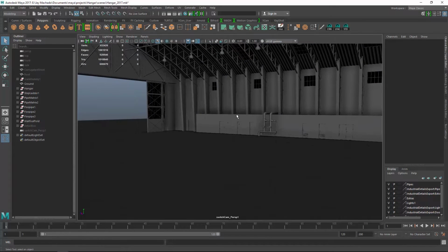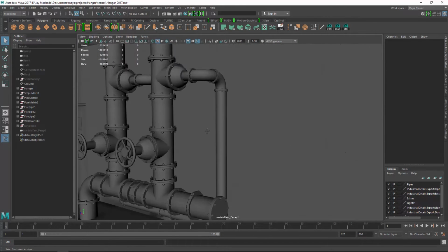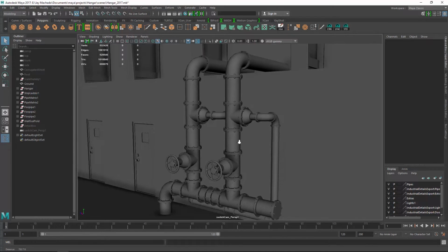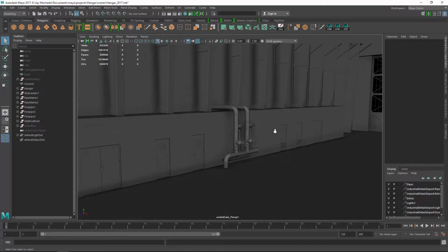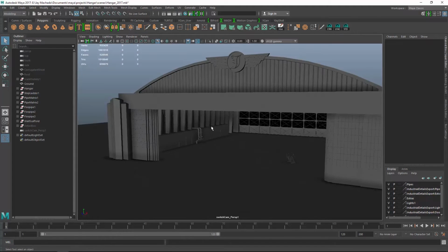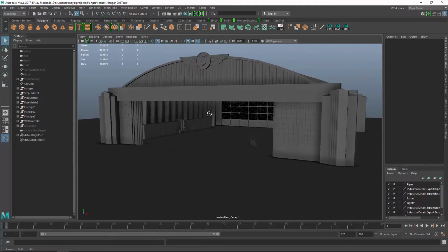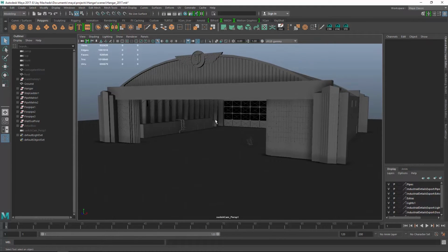The basic rule of thumb would be, if a fillet on your model is less than a pixel wide in your renders, they're not going to show up and they may as well not be there. Now, it's a little difficult to quantify this when you're actually modeling, but nowadays I'm much more inclined to keep the model as light as I can and add resolution later if I happen to need it. I'll get more into this philosophy later in the class.